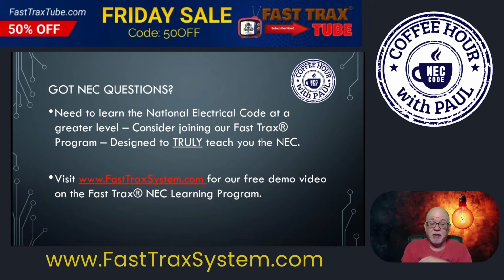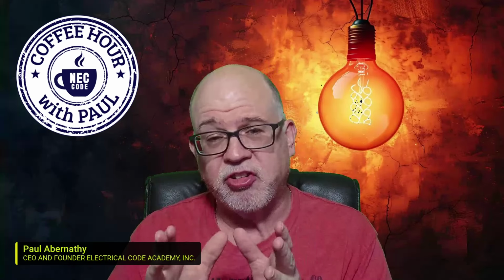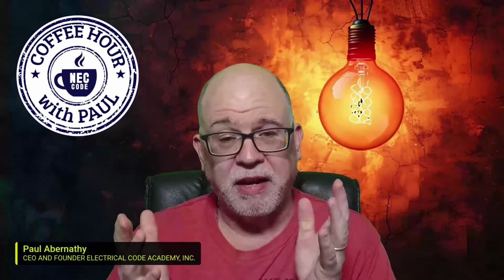Hopefully you got something out of it. Very quick video explaining ambient temperature correction and how you would apply it and how to do the calculation even if that wasn't a condition. It's pretty straightforward. The conductors for a single motor, a continuous duty motor, can't be less than 125% of the FLC. You do not use the nameplate amps when you're sizing conductors, okay?